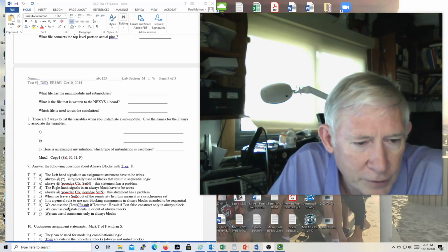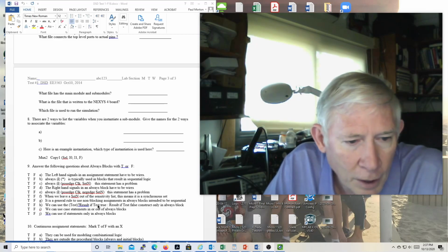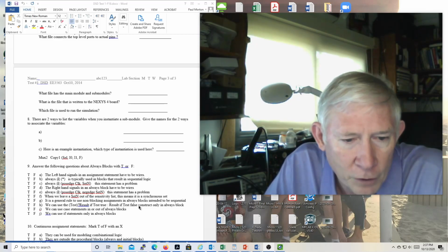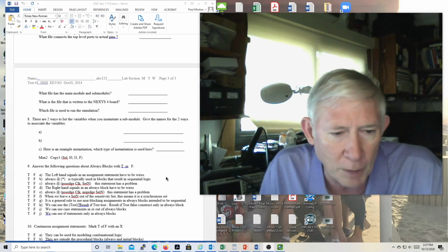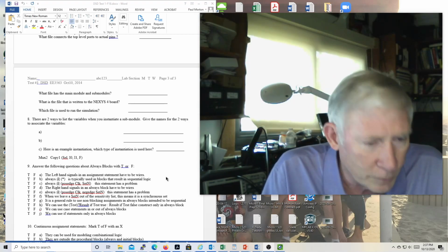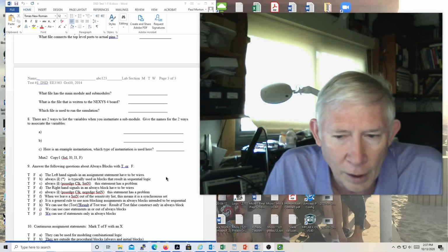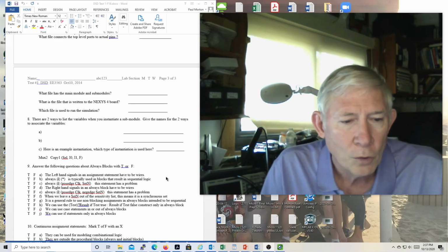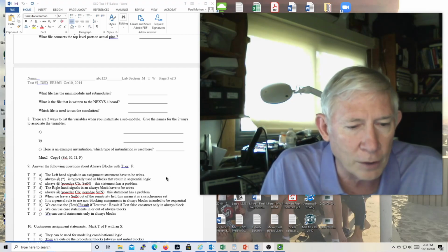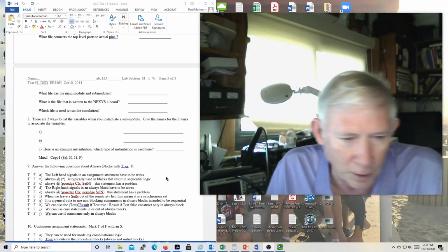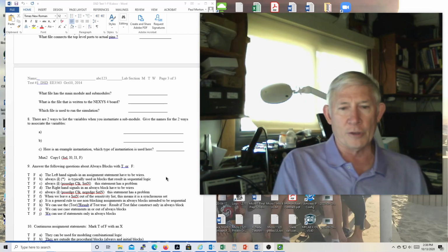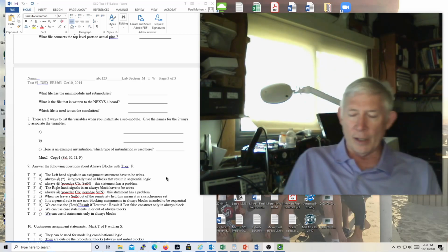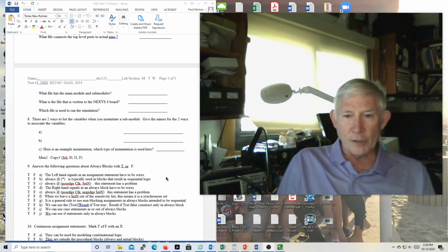We can use the test ? result if true : result if false construct only in an always block. No. We can definitely use that outside always blocks. That's the question mark colon syntax, and you can nest those too. We can use case statements in or out of an always block. Nope, that's not true. They must be inside an always block. We can use if statements only in always blocks. Yes, that is correct. We can only use if statements in always blocks, but you can use them in an always block, and then they don't necessarily have to result in sequential logic. They could result in combinational logic.